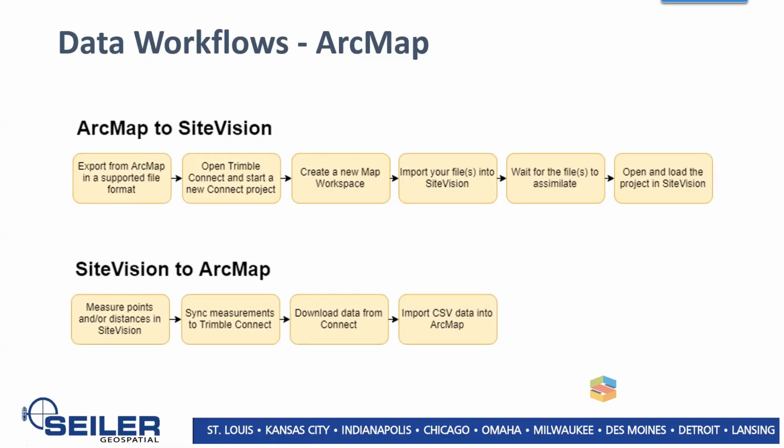This is the toughest part, to get that data into Connect, because once you're in the field, you saw that video from Mark. The longest part with using SiteVision out in the field is that you're going to wait for it to get GNSS and get its orientation. As you notice, there was one part where it asked him to walk 10 yards because it wants to get its bearing, so you can turn around and you don't have to worry about reloading your images and refreshing, because it's automatically going to do it for you live in the field.